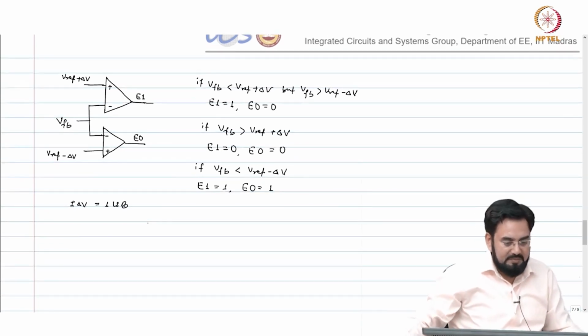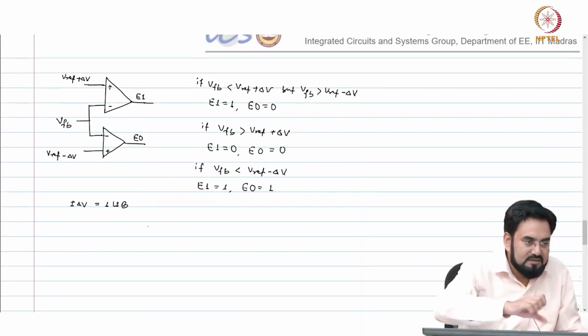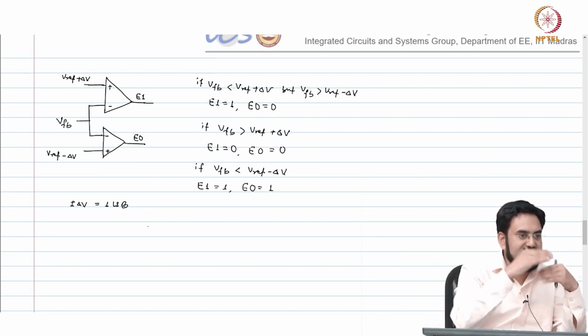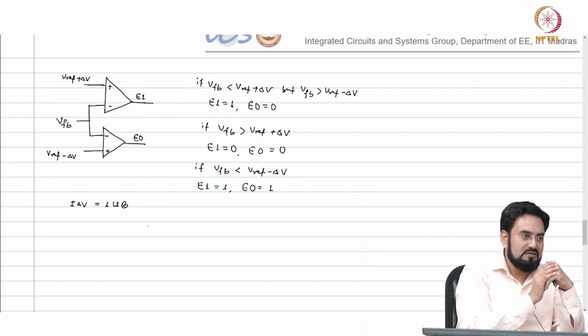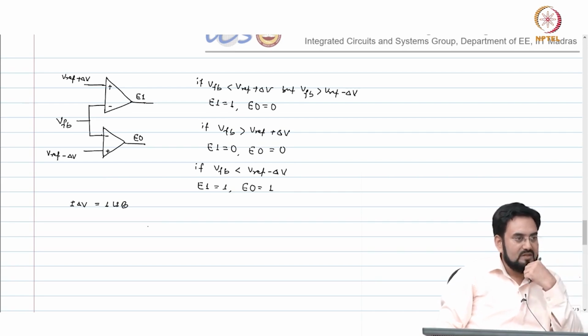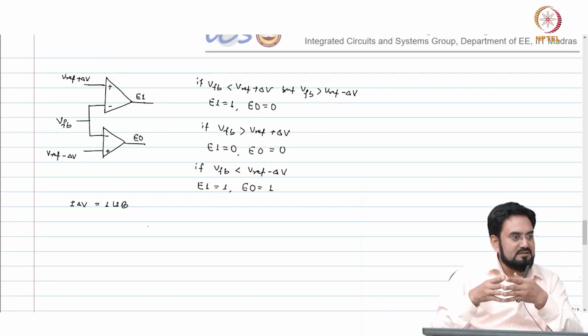So, now what would happen? We know my comparator output, or my accumulator, I want to change only when it crosses that window. When my VFB remains within this window, what I will get is 1 0. So, I make sure my accumulator code only changes when I get both 0 or both 1. So, when it is both 0, I treat it as -1.